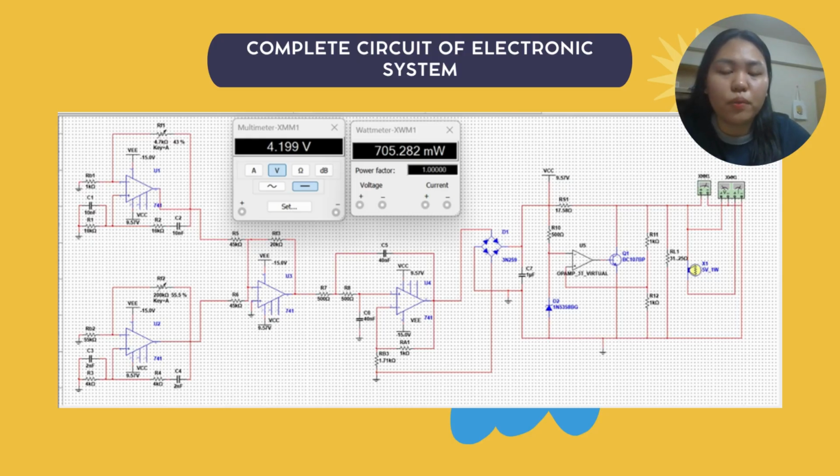This shows the complete electronic system circuit, including the power supply, amplifier stage, and output load. It integrates all key components to form a working DC power system. On the right side, we have the power supply unit. It converts AC to DC using a bridge rectifier, filter capacitor, and voltage regulator. The diode bridge converts AC to DC. The capacitors smooth the output.